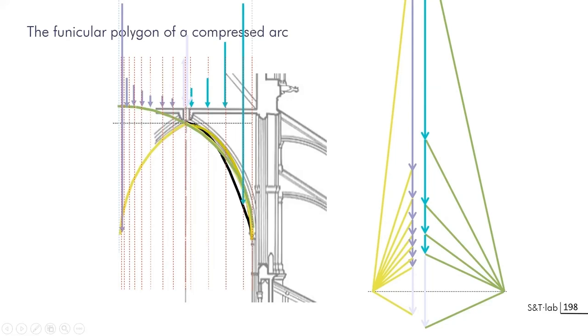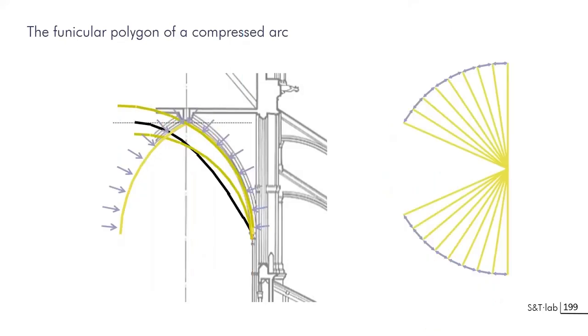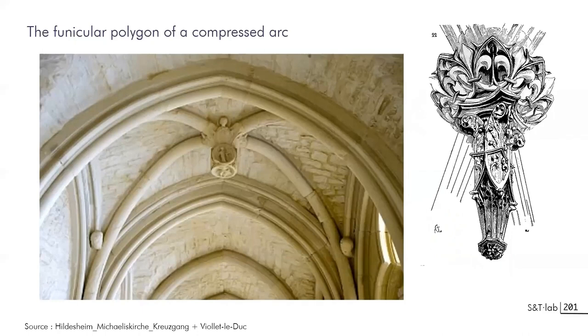You can use also this kind of system, and if I'm drawing a kind of pressure line, it doesn't make sense. It's just for the exercise. You see that it's not closed, but this will reveal that you will need other forces in the middle. And that's the case also with the pointed arch we have seen before. And one of these applications could be what is called the hanging keystone, that is an additional loading at the very middle of the arches. You have examples of several approaches. This will be in Paris also, in Saint-Laurent and Saint-Eustache on the right, that will give you elements of equilibrium.